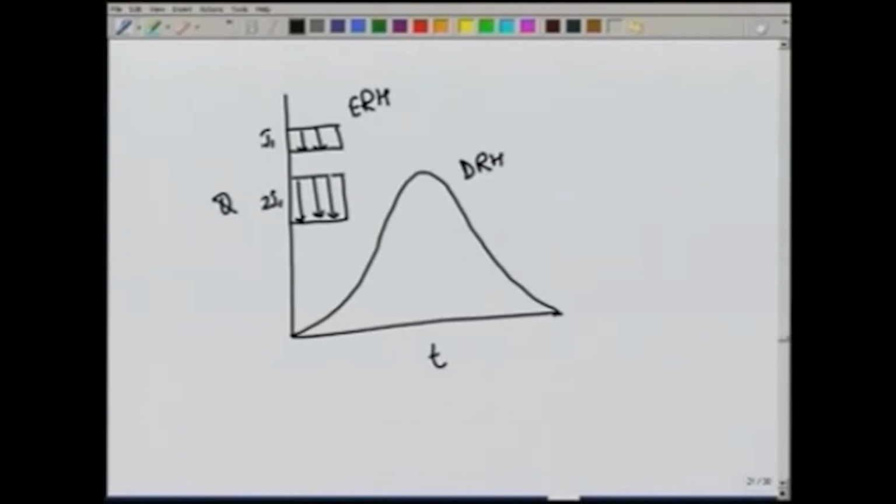So, the principle of linearity says that the direct runoff hydrograph because of the second rain with intensity 2 I1, the ordinate of that hydrograph will be exactly twice the ordinate of the first one. So, everywhere if you take the ordinates, this ordinate will be twice this ordinate if the rainfall intensity is twice.